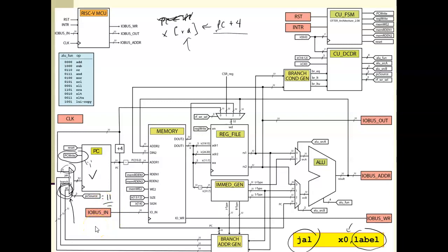Okay, all the other instructions, like I said, I didn't go over them. They all assert the PC write in the execute cycle, and they are choosing the next instruction because it's not a program flow control instruction. So the other part of this instruction is I need to take that PC value here. PC value, you can see PC plus 4.